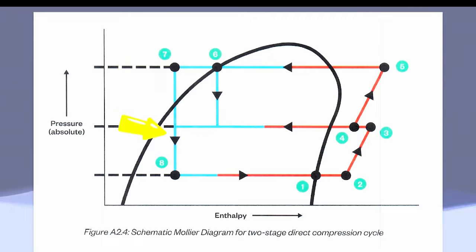As you can observe, the section from 7 to 8 is where the expansion valve is. There is a sharp drop in pressure. Well, from 8 to 1 is the return of the liquid to its initial state and evaporation in the tank. I hope everything is clear here.